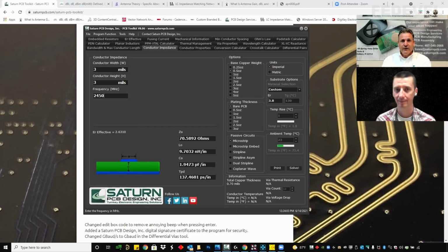Well, because it's not just manufacturing tolerances. One of the big things that happens, especially in FR4, you don't see it in the Rogers materials for the most part, but in FR4, if you have a multi-layer board, your dielectric constant can go down significantly after the pressing phase of the board.